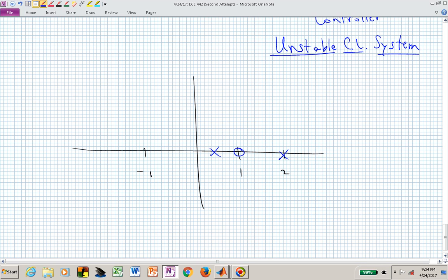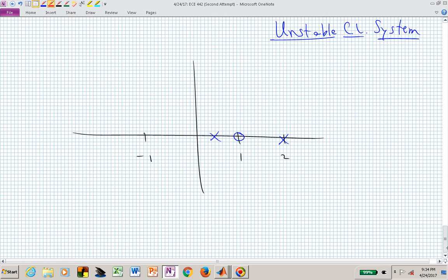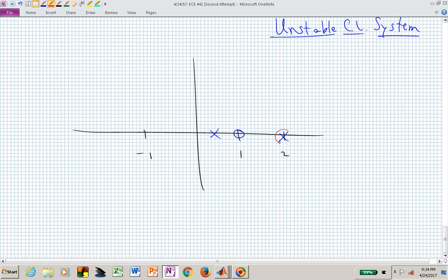It has 2 poles, one inside the unit circle to begin with at 1/2, the other one at z equal to 2, and we have a pole at z equal to 1. What we're trying to do then is eliminate that root locus branch that was living between 1 and 2, or at least allow us some opportunity to not be stuck there for all time. If we were to put a 0 there, what would happen?